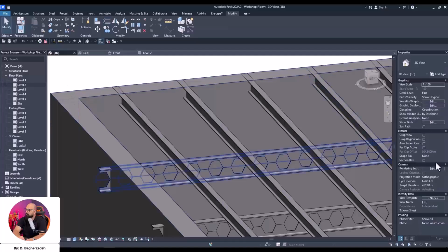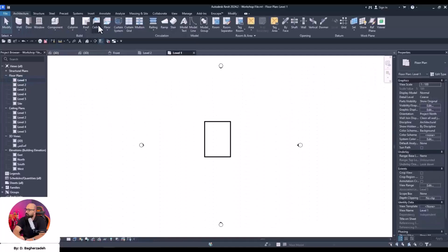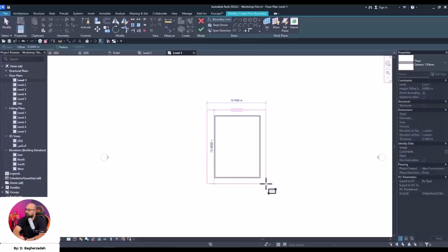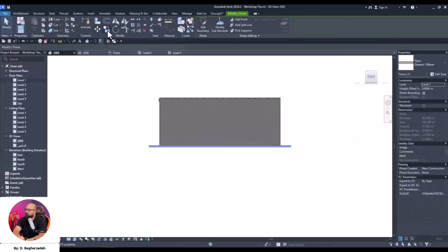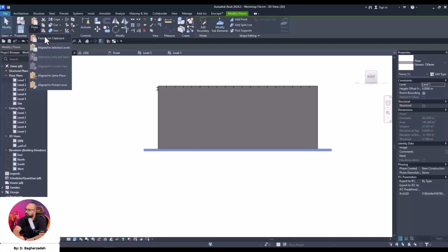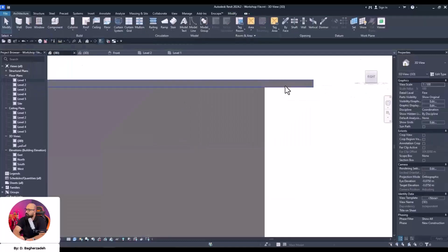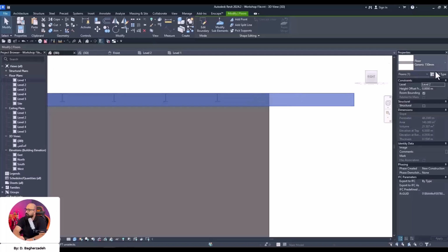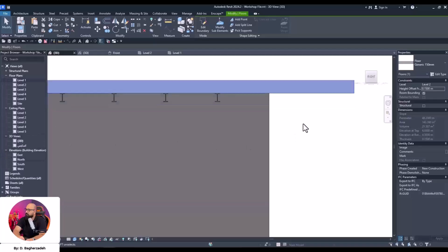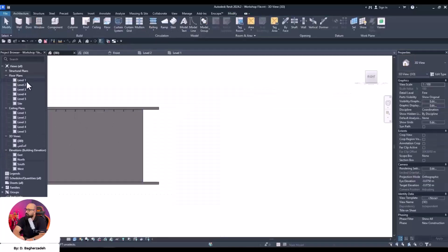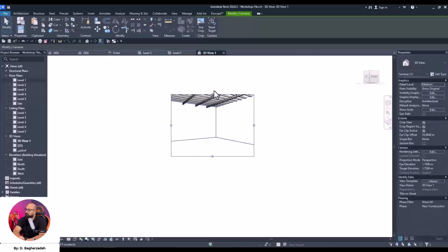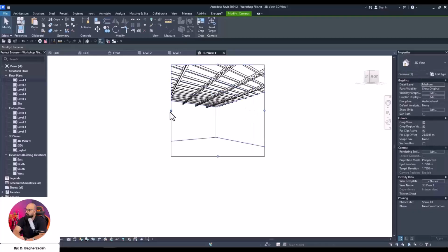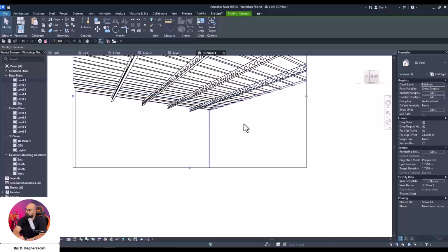You know what? Let me try to elaborate on this. What I'm going to do is I'm going to use floor tools here to draw something like this here. Then I'm going to use the same floor here, this time in the second floor. Right now I want this to be set a little bit higher. Let's assume that the thickness is 15 cm. I'm going to give it a 50 cm offset. Again, completely hypothetical. Right now, if I go back here and set a camera in this angle, what we'll see would be this, well, beautiful, and you can even say quite detailed ceiling, okay?